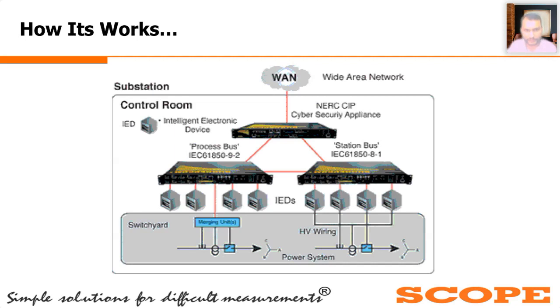All relay signals are hardwired to those IEDs, and from those IEDs they are connected to the switches over a certain protocol. Normally in a substation environment, the IEC 61850 protocol is preferred as a standard. So over IEC 61850, it will be connected to the switch, and the switch will be connected to the servers.